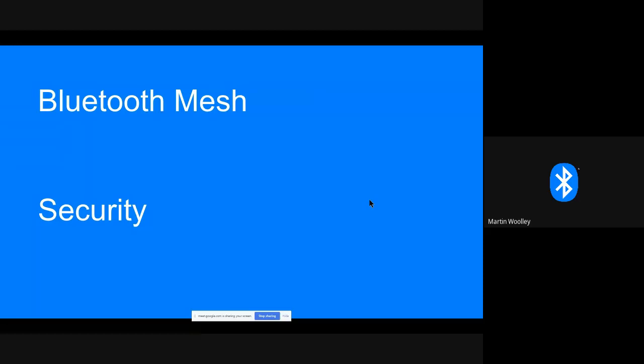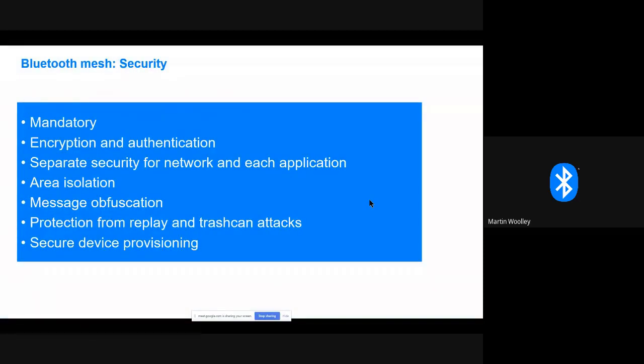Very briefly, let me talk about security. It's a big subject, of course. I have some bullet points here and some more information on the next slide. First of all, you'll probably be aware, if you've worked with Bluetooth Low Energy, with GATT and GATT Bluetooth peripherals, those kinds of things. In that world, security is actually optional. We don't mandate security in that use of Bluetooth. The point being that we don't know anything about the security requirements a manufacturer might have for their particular product, used by their particular types of users in whatever circumstances or conditions. So Bluetooth Low Energy for connectable devices gives you a toolbox of security capabilities, but it's up to the manufacturer to select from that toolbox those security features they think they need for their product, having done their own security assessment. That's how it works.